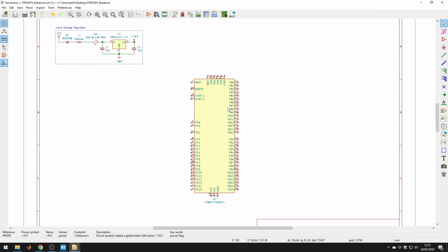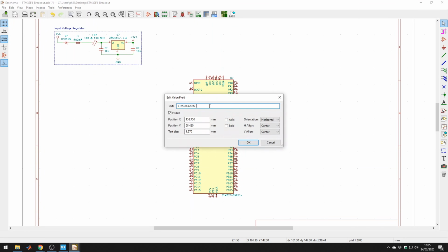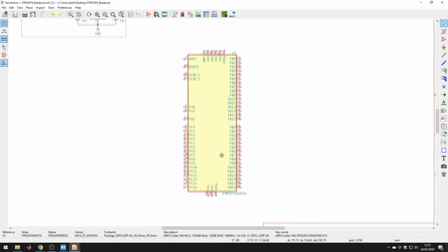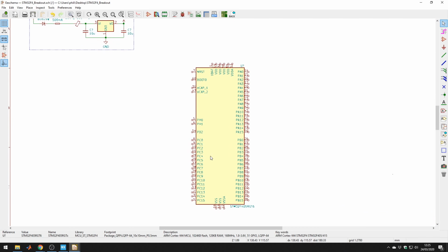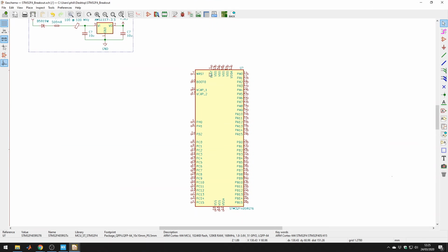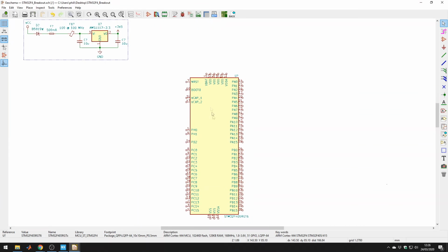Let's look at our microcontroller. This is kind of the more interesting part. Let me just move the labels around, make it a bit neater. I already know we're going to be using the RGT6 version here, because that's available at JLCPCB. Since this is a KiCad standard library, it's really quite nicely sectioned. So we have all the VDD, the positive voltage rail pins up here, the ground pins down here, and sorted into various banks, A, B, and C banks, and various other circuitry.